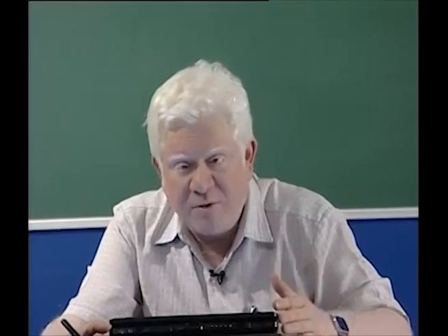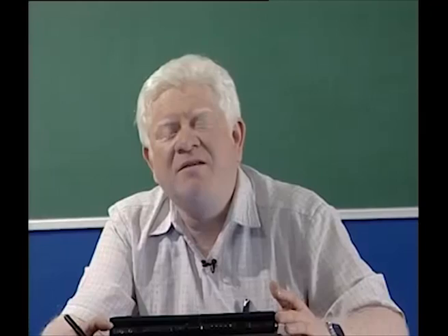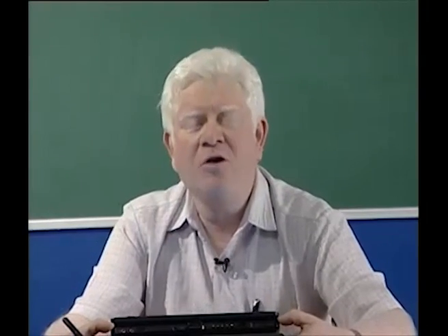Now, we are asking a similar question: can we look at a differential equation and say whether the system that is described by it is causal or not? Here again we find that what a differential equation says about the system is not exhaustive. The differential equation's description of the system is not exhaustive. It does not constrain the system to be either causal strictly or anti-causal strictly. The system is free to be either of these.